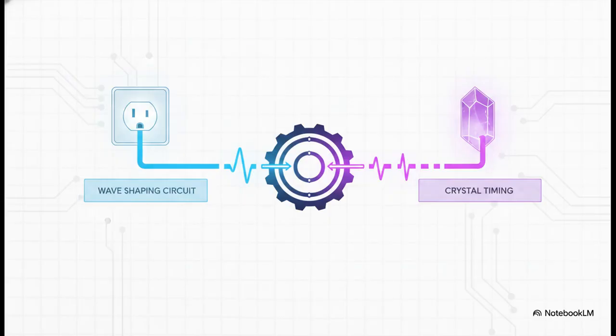This ensures you get a stable, flawlessly clean image on the display without seeing the beam's return path smeared across the screen. Now, you might be wondering, how does a localized system keep perfect time if it doesn't have a master broadcast tower to rely on? Well, it gets incredibly clever. For vertical timing, it taps directly into the standard 50 Hz mains supply frequency, running it through a wave-shaping circuit to trigger the vertical oscillator. For the horizontal timing, it utilizes a crystal-controlled, astable multi-vibrator. That component fires off a series of precise clock pulses to lock the entire timing sequence in flawlessly.